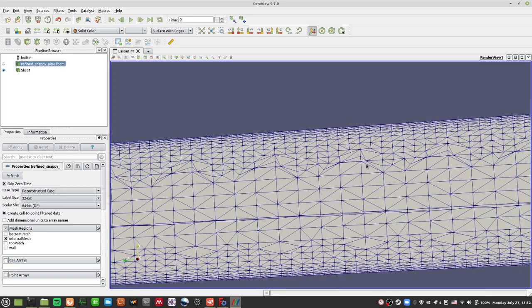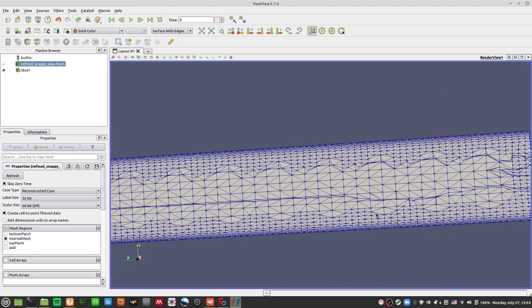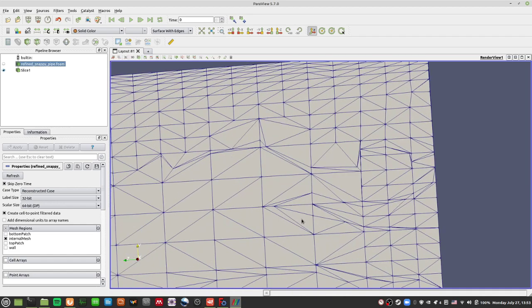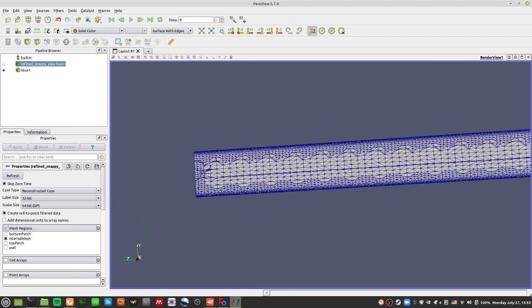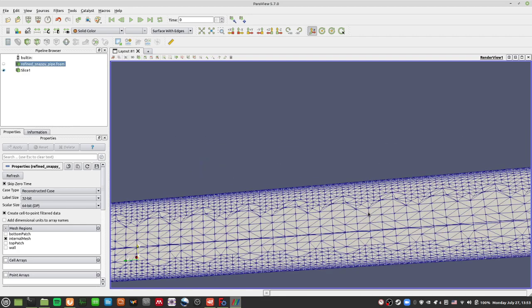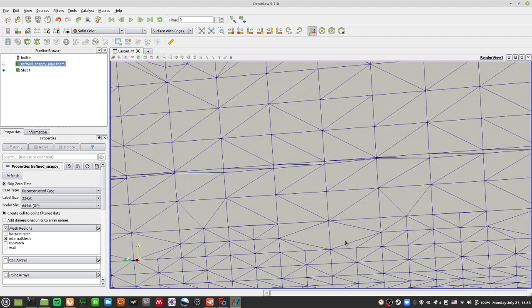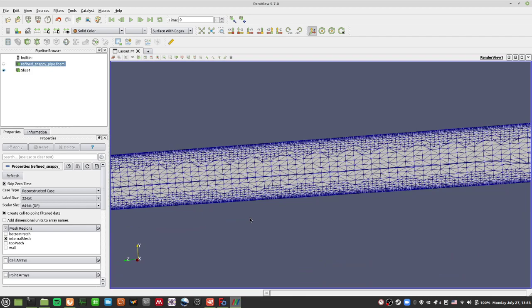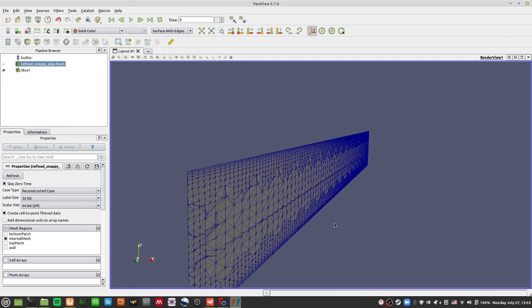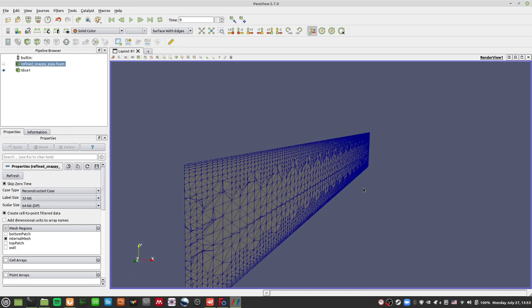Is there anything we can do about all these strange shaped cells? Well, if we don't adjust the mesh quality, there's nothing much we can do, but we can of course tweak it. So this is generally the mesh that we kind of want. We may want a coarser mesh for more stability next time, but as of now, this is what we are left with. You see these things are so small. I don't really like too small meshes. They generally contribute to more instability.